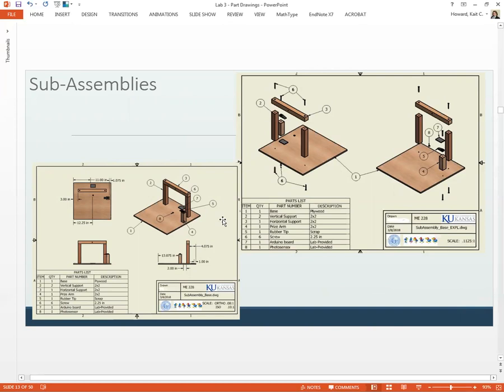But you'll use those parts to come together. And that's part of why having parts be fully defined is going to be so important. As you're putting your assemblies together, it'll matter. And it'll also matter that you use the correct dimensions. I would suggest using parametric equations so you can pretty easily change a whole bunch of dimensions at once if you need to. That's why we're learning it kind of in this order.